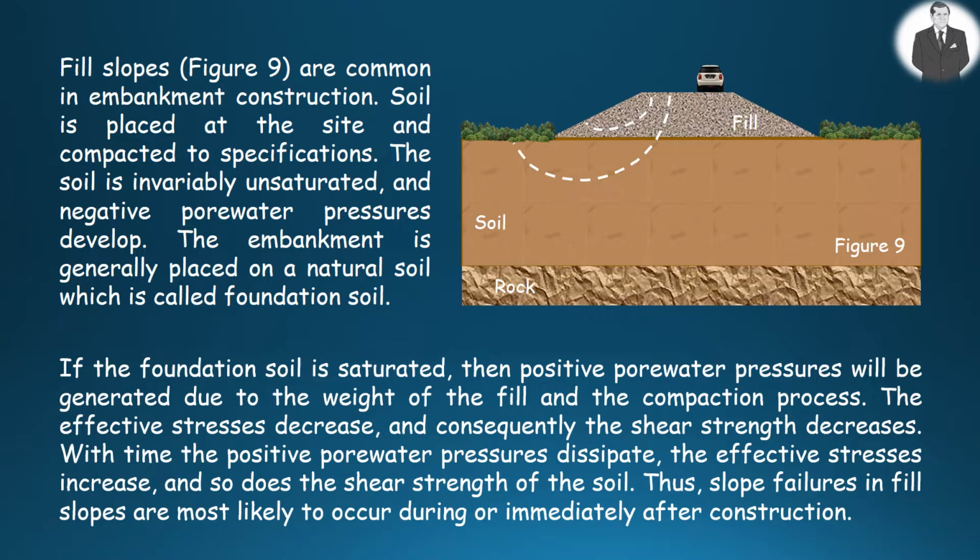With time, however, the positive pore water pressures dissipate, the effective stress increases, and so does the shear strength of the soil. Therefore, slope failures in fill slopes are most likely to happen during or immediately after construction.